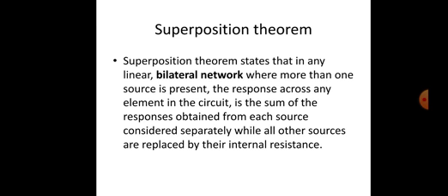Superposition theorem states that in any linear bilateral network where more than one source is present, the response across any element in the circuit is the sum of the responses obtained from each source considered separately, while all other sources are replaced by their internal resistance.